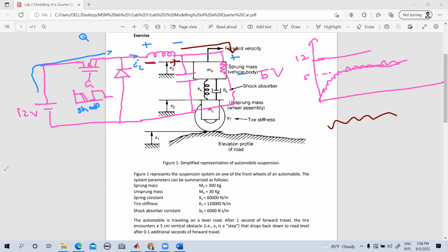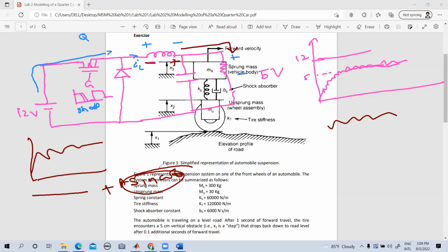You know from Fourier series, if there's a signal, the signal has a DC component plus a collection of harmonic oscillations, or you can say A sin omega t or cos omega t. This AC part will go through this capacitor. So we'll be able to remove this ripple through the capacitor, and we'll be able to supply this DC potential, DC current through the resistor. This is the overall objective of using the LC.